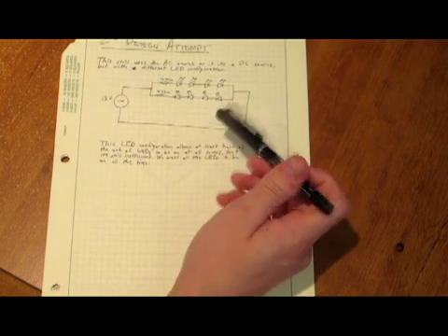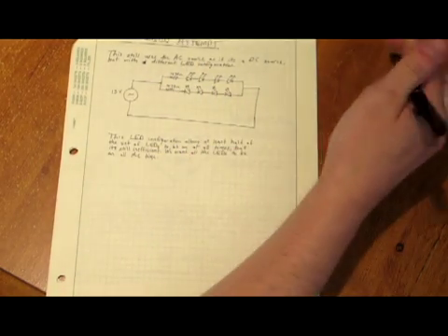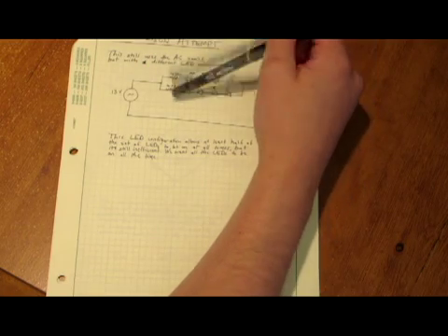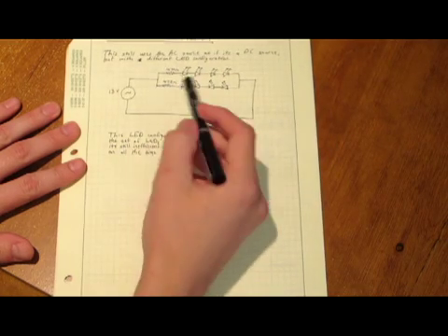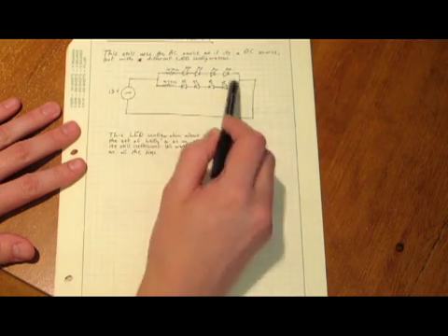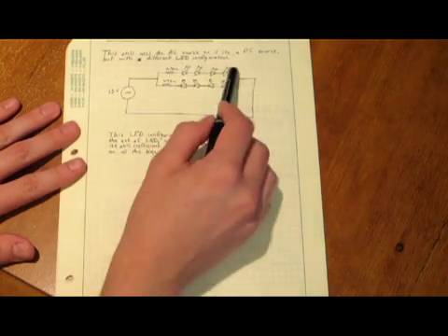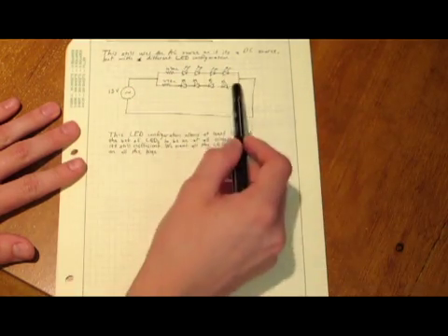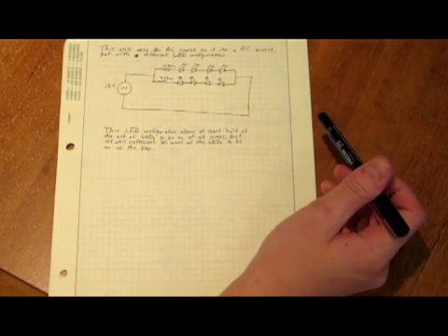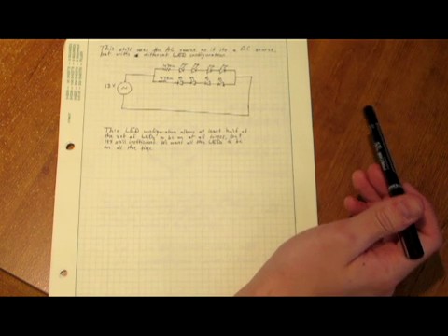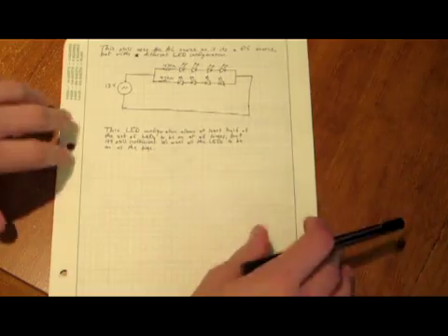So our second attempt is to take that same circuit and make one of the series of LEDs go in the opposite direction. So you'll still have your current limiting resistors, and what's happening here is current's going back and forth like this through the circuit. So at all times, at least half of your array of LEDs will be on, because the current will go this way and these will be on, and when it comes back this way, then this set of them will be on. But this setup is still inefficient because you're powering an array of LEDs and you're only getting half of them on at any given time.